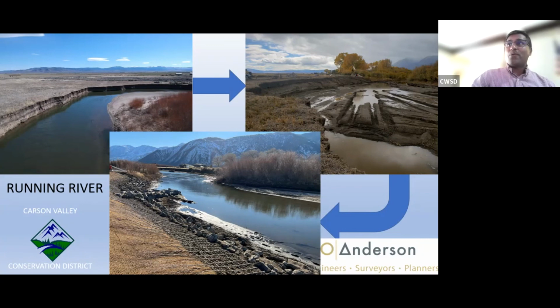It's not going in the river anymore; it's just going the other way around. So we realized they didn't compact it well, and didn't put some rock at least to stabilize that newly placed fill. We had to go back and get that fixed. So those are the things that we had to deal with if you're not there every single day watching what's happening, I guess.